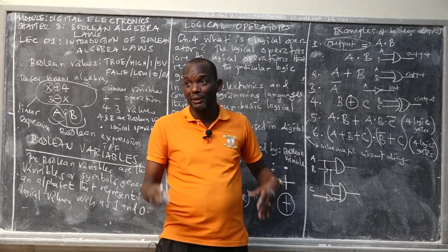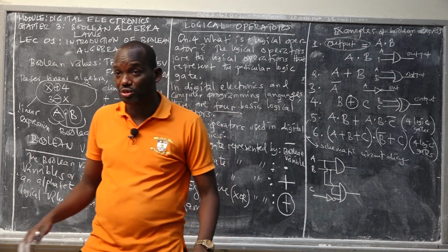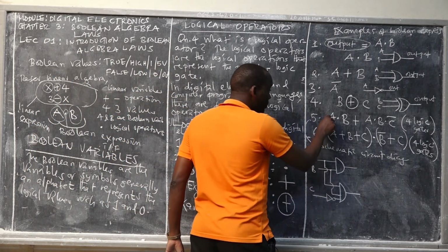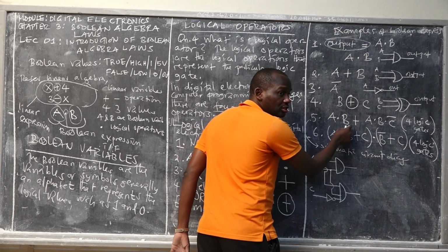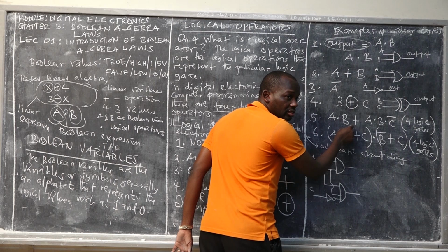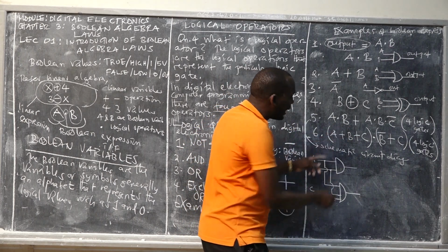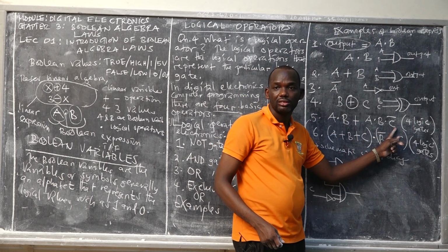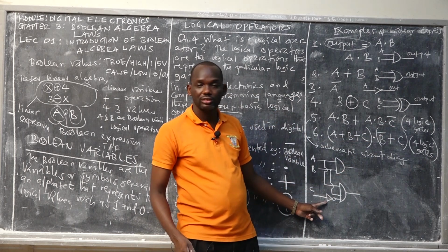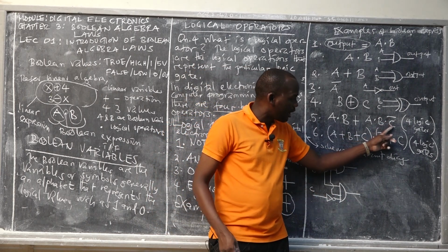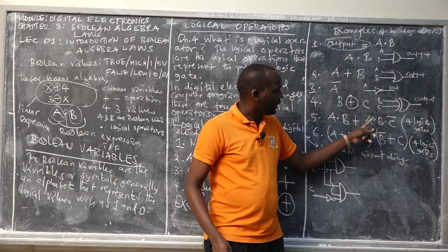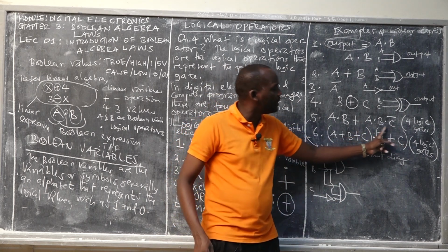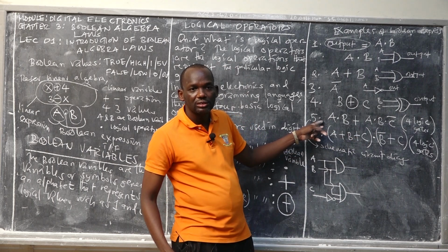Be careful, because you may just draw plus, plus, plus, or, and a lot of them, and then you get confused. Look here. This one is an independent input, and this one is an independent input. So we have A and B. This is the single logic gate. Then the output of this gate will be ORed with the output of this combination. But here we have the NOT gate first, that's why we have the NOT gate on C, and B and A. Then the output of this logical combination is ORed with the output of this one.